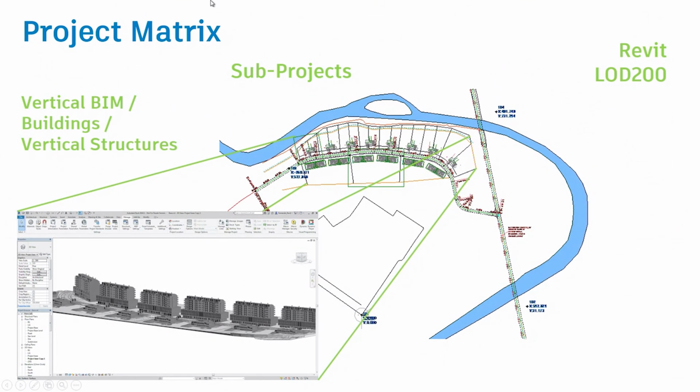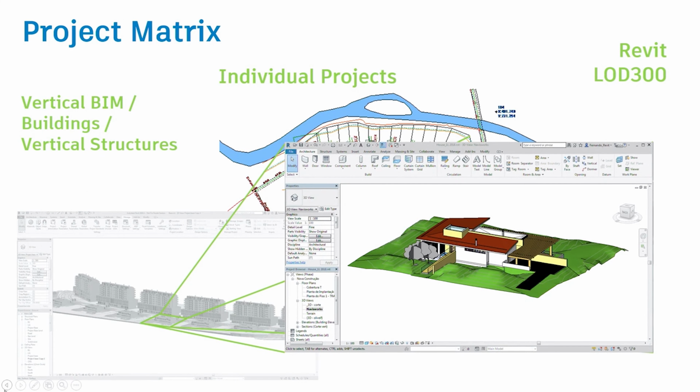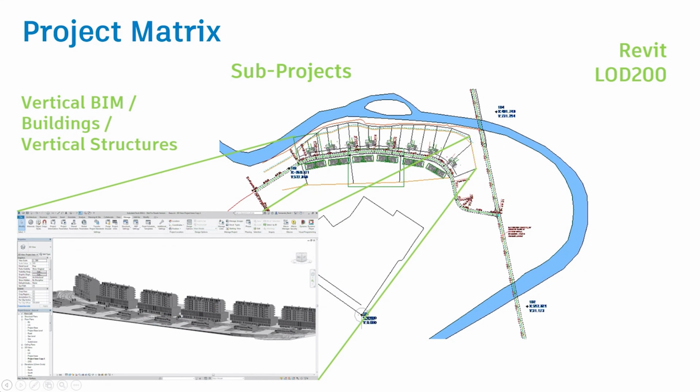So let's go to my part. As Lucy established our project in Civil 3D, I start to establish my project in Revit. I will show the file itself. We create a big zone of interest. We call it the base project file, let's say, where we can establish the coordinates with our GIS information. And then we start to link Revit files there. We had 3 methods, and that's what we're going to talk about today: how to link Revit models in our big project. We had individual projects already developed, and we had assemblies of groups of buildings that are also created.